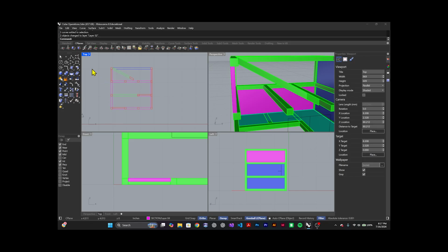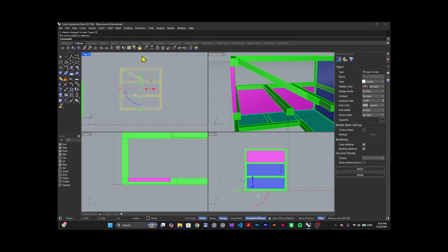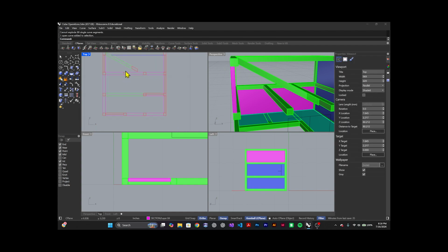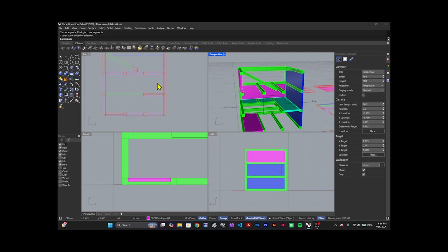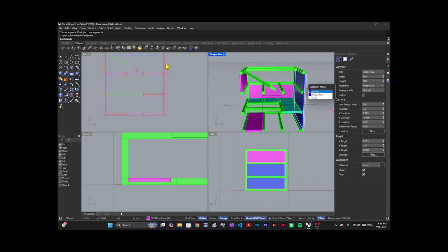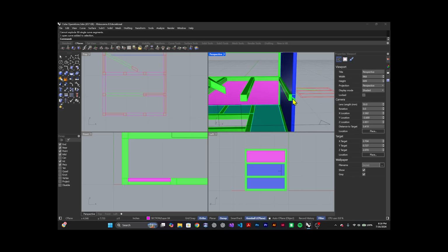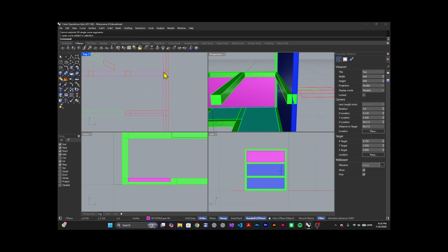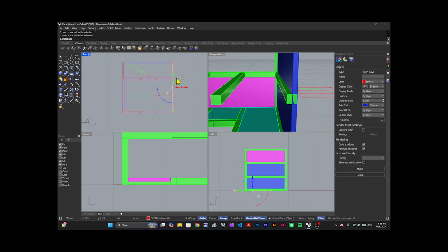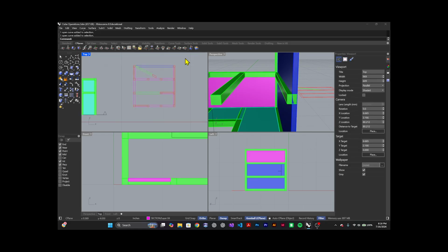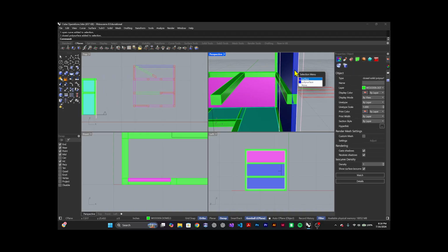So now we need to do some cleaning of the drawing, right? So I'm going to select everything, and then I'm going to ungroup everything, explode everything, so that way we have just different segments, okay? Just to make it easier for us. So now, remember, we have this plane right here. But this plane, this shouldn't happen. That's why you see this guy right here in the middle. We don't want that because the planes do not intersect the structure.